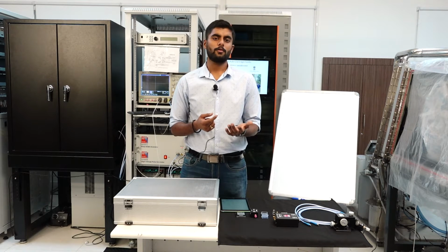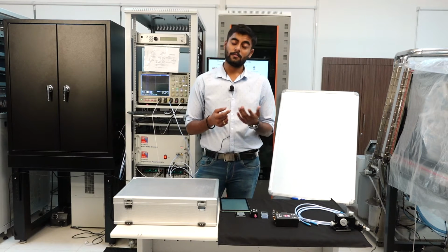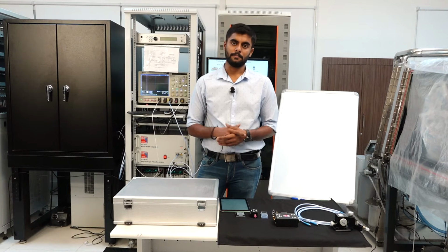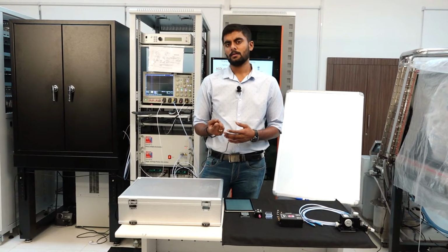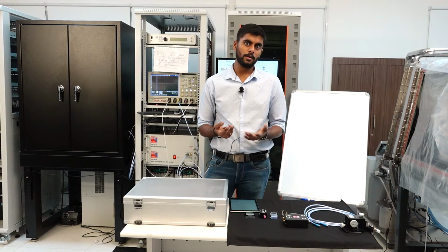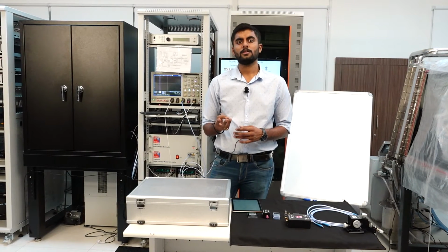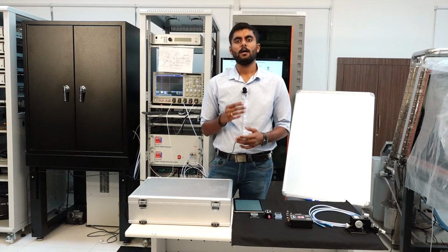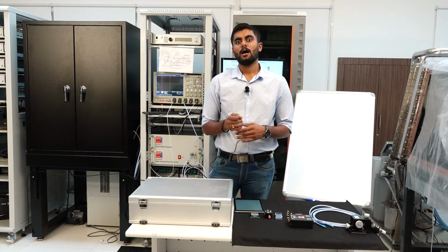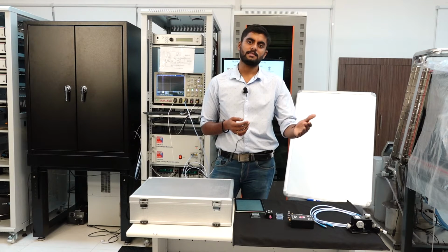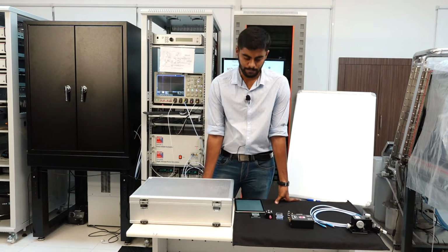So you need to have a good control over the waveforms as well. If you wanted to say apply a square wave and it's coming out as a triangular wave, then your whole measurement is ruined. So you need to have a good control over the whole waveform that is being applied. You need to have a good control about the amplitude, and you need to be very careful about the on-off times, because depending on these on-off times will depend how much heating you're applying to the signal and how much your device is on and off, and all these different non-ideal effects would then get related to the on-off times.